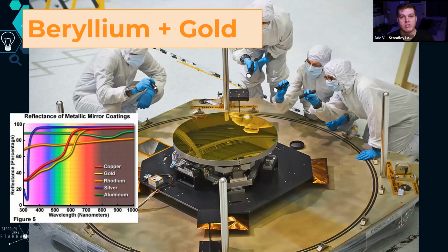So that pretty much rules those out. Gold, however, it's a little bit heavier, but it is also comparable reflectance, and it's very inert. So it can survive extended periods without oxidizing with effectively anything. So it's a perfect candidate for coating the mirror in this use case. So that is why they opted to go with the gold.